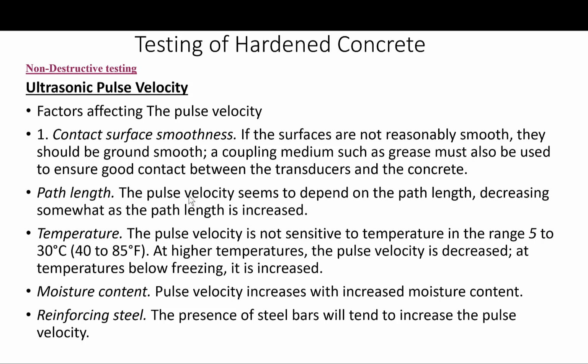The presence of reinforcing steel bars will tend to increase the pulse velocity. Also the concrete age: for a given compressive strength, the pulse velocity is lower for older concrete than it is for newer concretes.